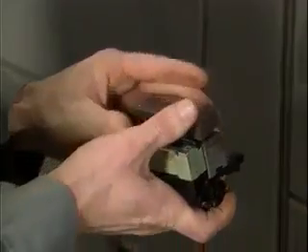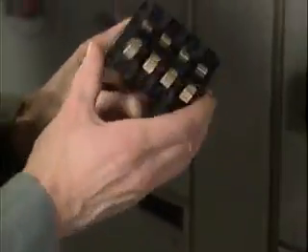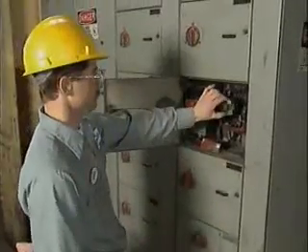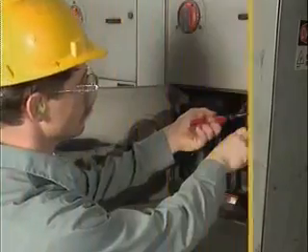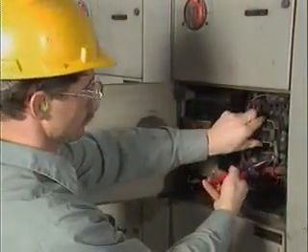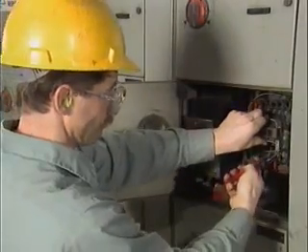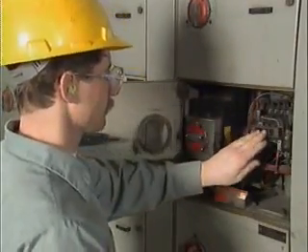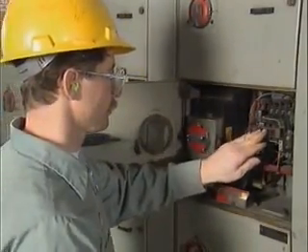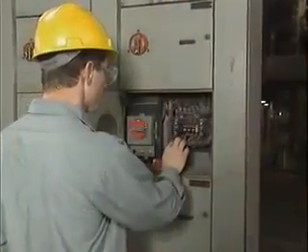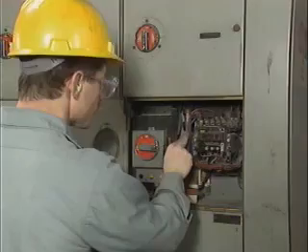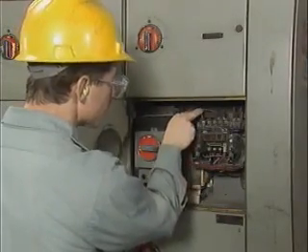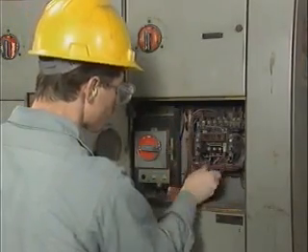After the contacts and armature have been examined and any necessary repairs have been made, the movable contacts can be reinstalled and properly aligned. Once the contacts are in the proper position, the contactor's armature can be manipulated by hand to check for free movement and proper operation of the contacts. After you've examined the contactor and its parts, you should carefully examine all of the other controller components to make sure that they are in good operating condition.